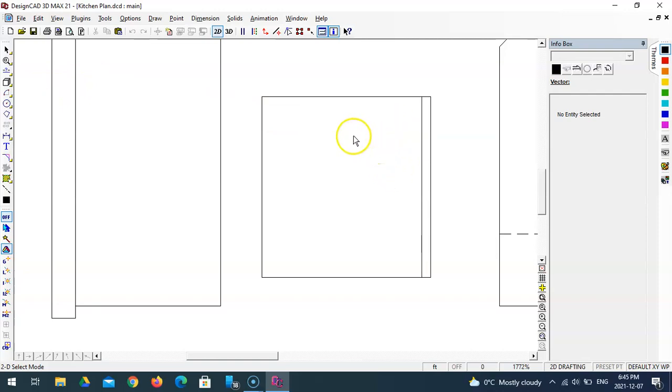Well, second next. I want to draw a little box here that's 2 inches down, 2 inches out, 2 inches down, and 2 inches in. And that's going to be the handle, which helps me indicate swing direction. So we'll grab the line drawing tool and simply use XY coordinates to get us there.